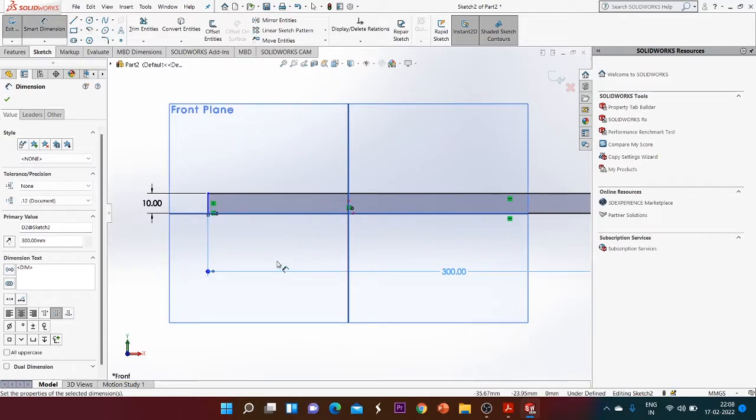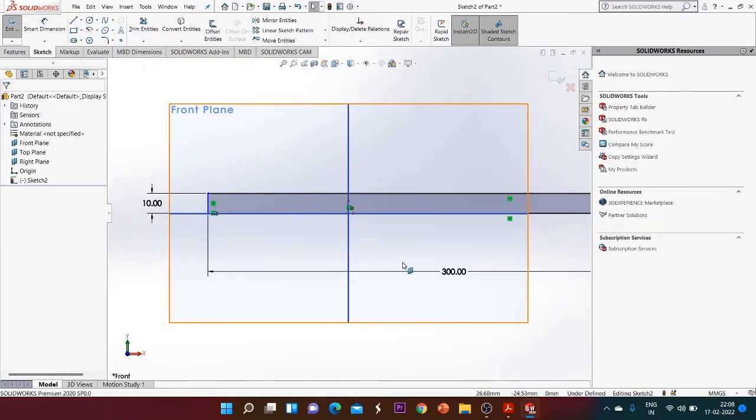Now here we can see that this has created asymmetry around my origin. To remove this asymmetry on the origin, you have to provide a constraint on one dimension from one direction to another. We have to make sure that our component is always symmetric about our origin.